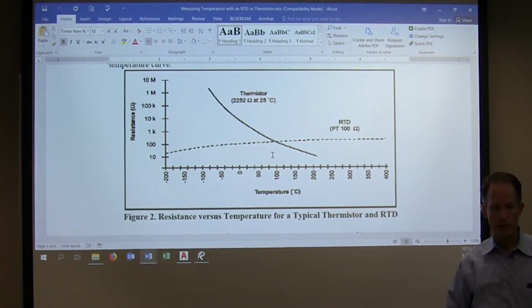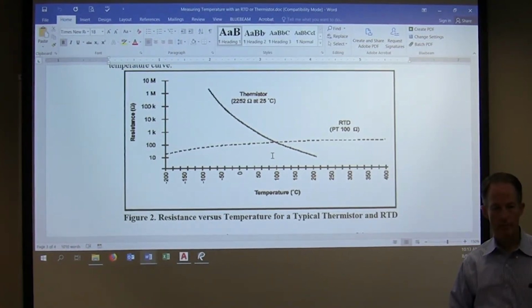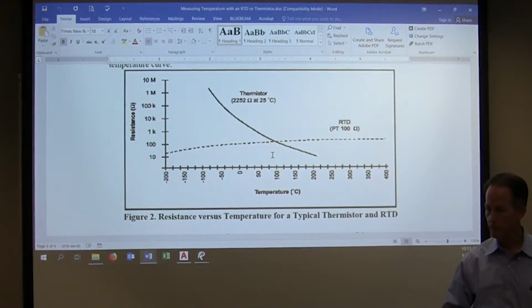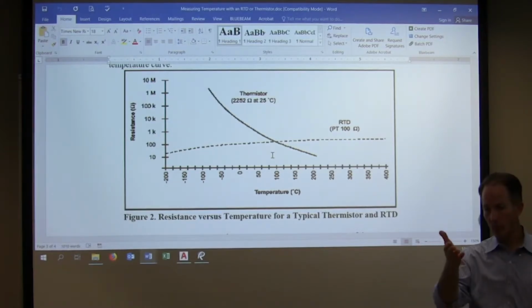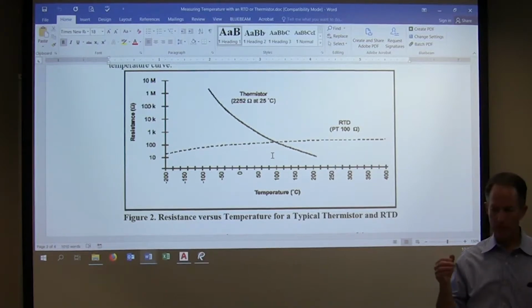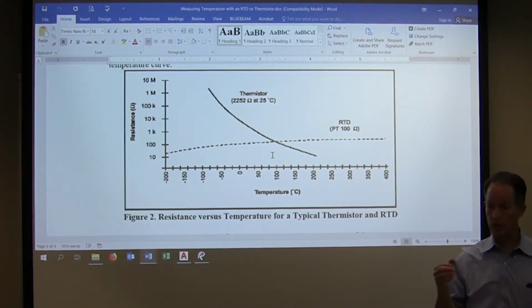What other sensors do you guys see out in buildings? Sensing bulbs, and they use a Freon. Okay, so we have a gas-based temperature sensor. We use them in freezestats, bulb stats, TXVs. Basically, as the temperature goes up, the pressure goes up.